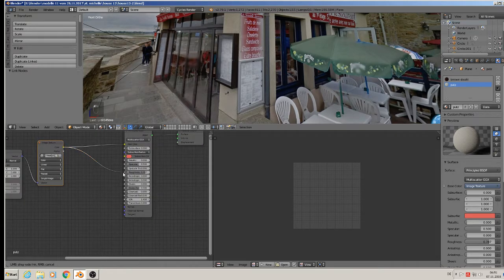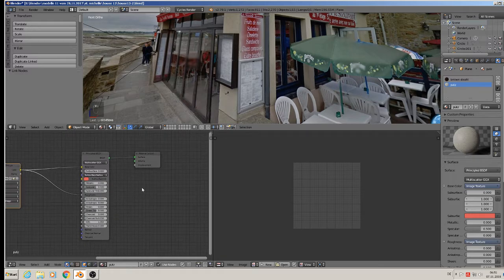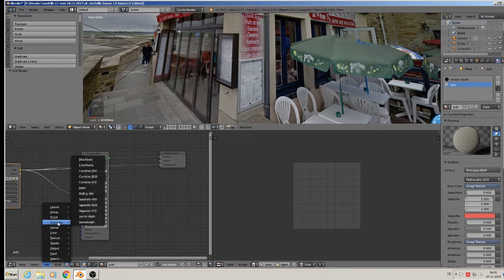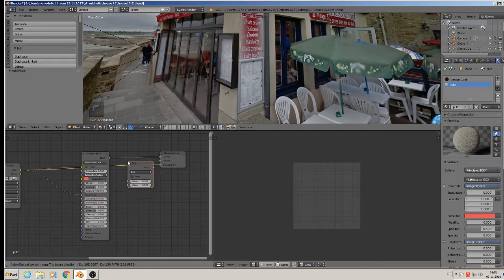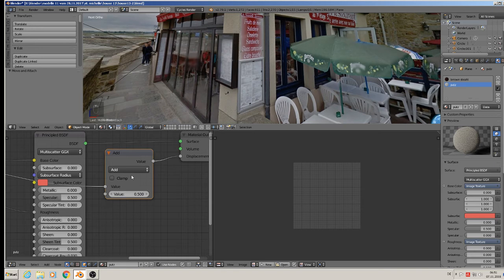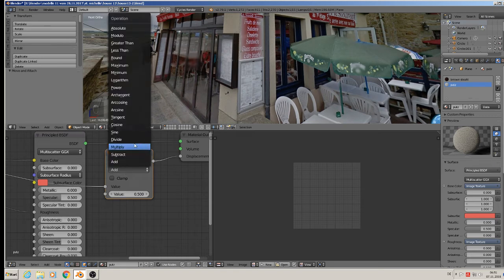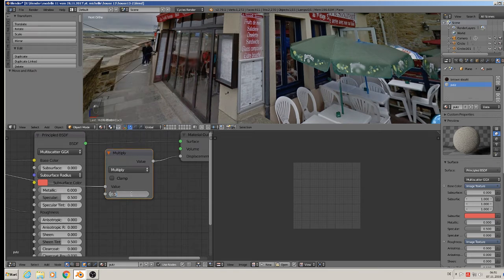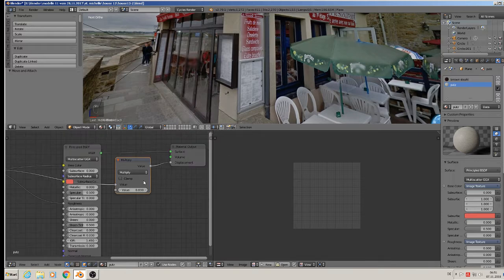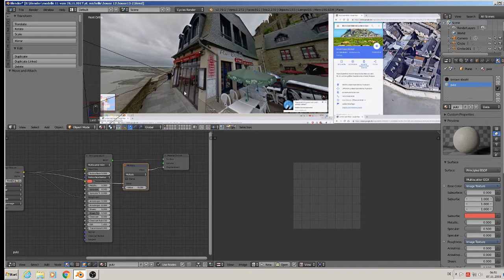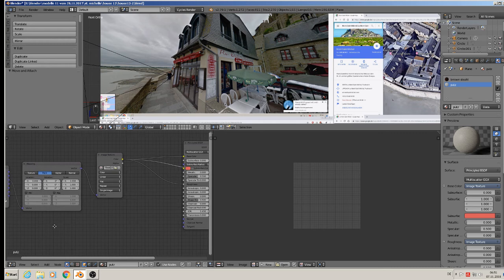So I try here to get the color as the roughness too and put them into the displacement, so we have more of the 3D effect. Then we get their converter, math converter between the texture and the displacement to handle their strength. So we go to multiply and give it a 0.3. So that material looks halfway better. Good. So we have that.